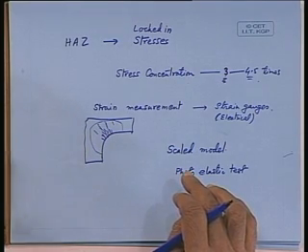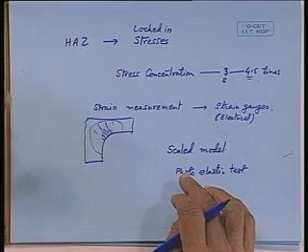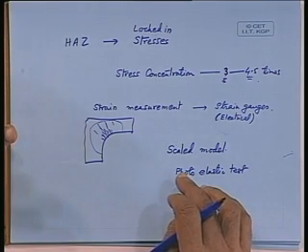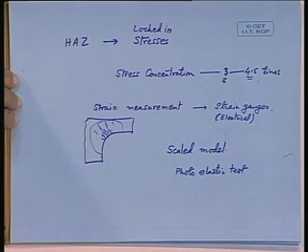So you have to have a photoelastic material in which you can conduct the photoelastic measurements. You will try to get the material which is isotropic, but it will not have similar mechanical properties to that of steel. So once again you will only try to get the nature of the stress concentration and the behavior, what type of structure you are taking and how you expect the stresses will follow.